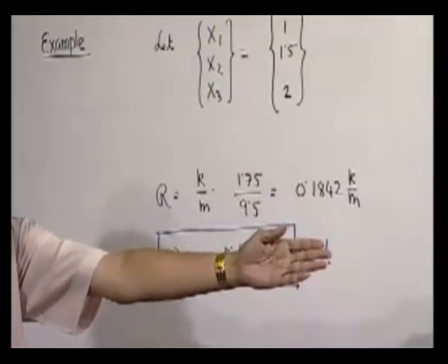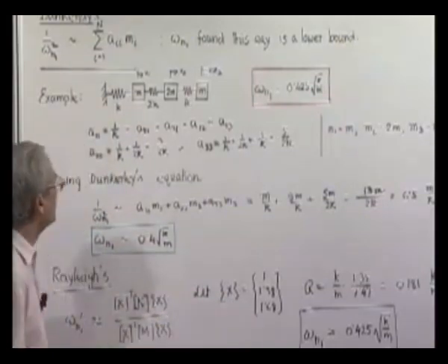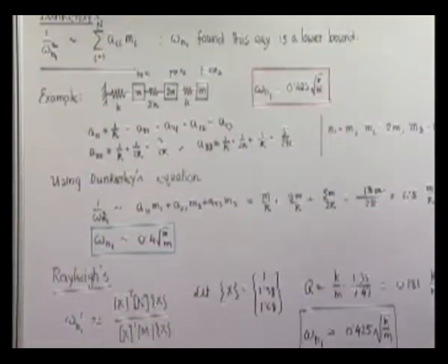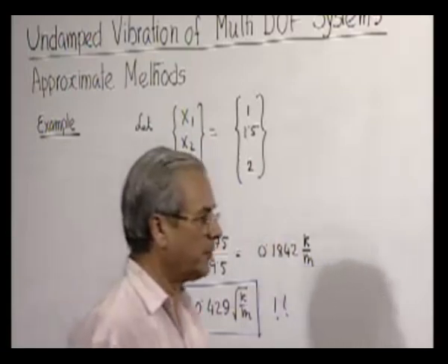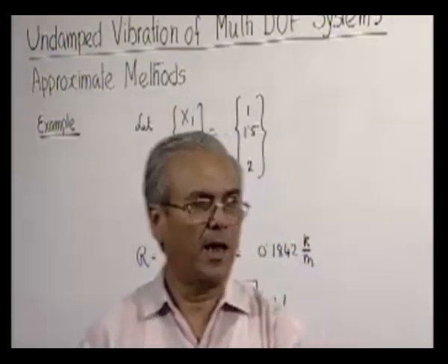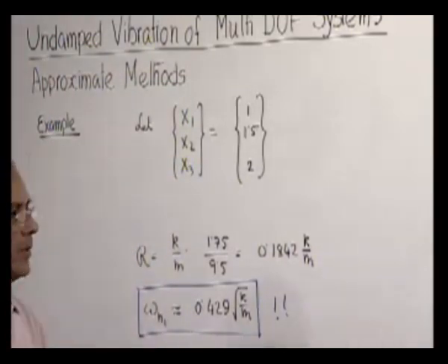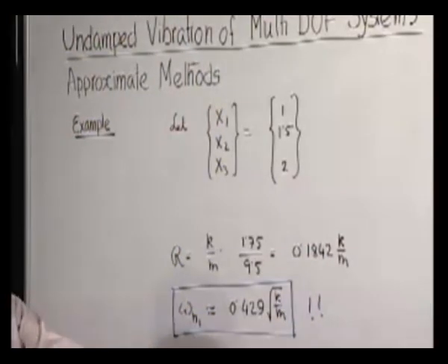This was also a static deflection case, it is not the actual mode. This is not the real mode. The real mode we have found in the previous lecture, you can compare and find what the real mode was. But even if you make this, you get some value, which is always more than the real value. That is why we always get an upper bound. The proof of why it is an upper bound can be found in standard texts, and I did not devote time to that proof, but if we understood the procedure, it will be good enough.